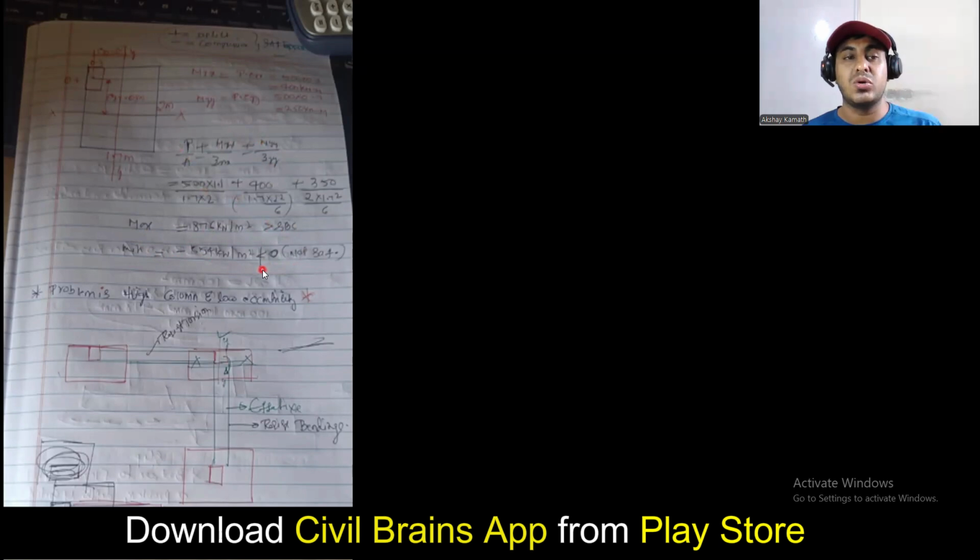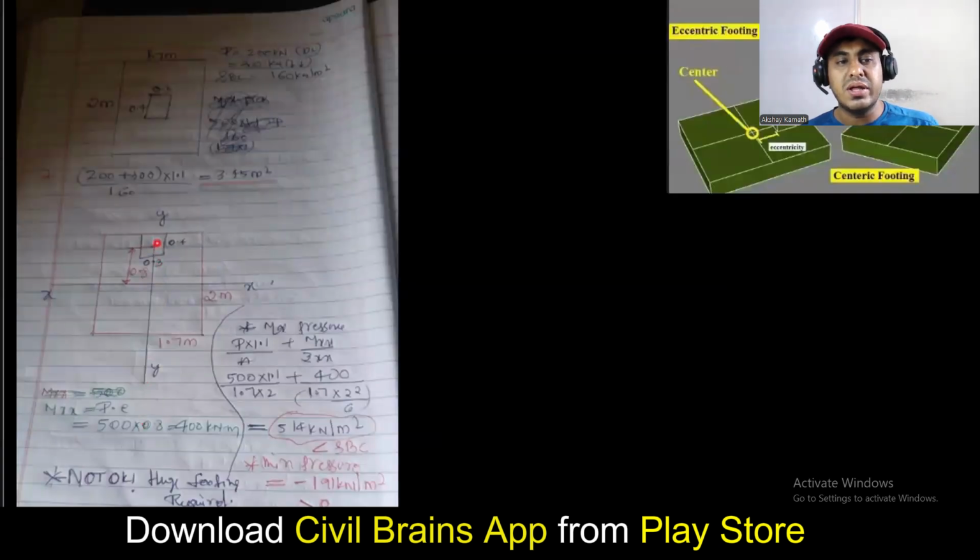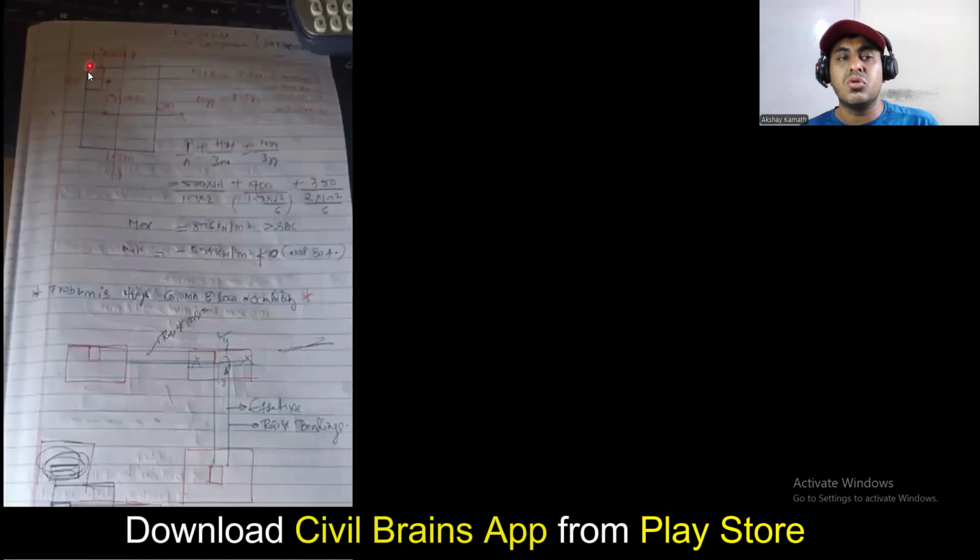Again, what I'm basically trying to tell is, when you have an eccentricity in both directions, your moment is going way beyond, and the maximum pressure and minimum pressure go way beyond. In the previous case, your eccentricity was in only one direction. So there your maximum pressure somehow you were able to satisfy, but minimum pressure you were not able to satisfy. But since here eccentricity is in both directions, you see your maximum pressure is 876, which is greater than SBC, and your minimum pressure is minus 554.